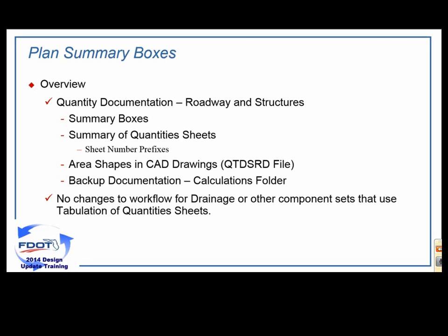through however many for the general, and those would be if there was any roadway type summary boxes that needed to be included because there isn't a roadway component. All other summary pay items would be in the summary of quantities for structures, and those would be BQ1 for structure 1, and all those quantities for that structure are on one summary box. And then you'd have BQ2-1, and there may be multiples, so you'd have BQ1-1 and BQ1-2, and so forth.